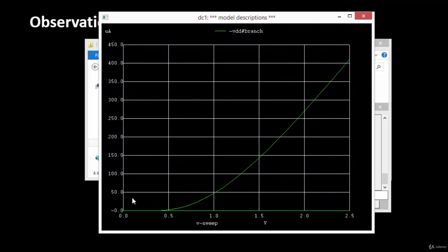So you have now this particular plot for the gate. This is the drain current, and this is your VGS, gate voltage, at one constant voltage of VDS. So VDS is held constant. So basically, if you see, there are two plots. One is this yellow line, which is at VDS equal to 0. There will be 0 current because VDS is at 0, and there will be one more plot which is at VDS equal to 2.5 volts. Okay, so if you see this one, this looks fairly quadratic, and this is not very obvious from this plot unless we compare this plot with the other one, with the short channel one.